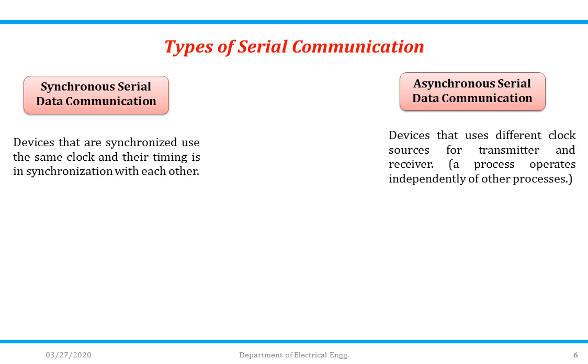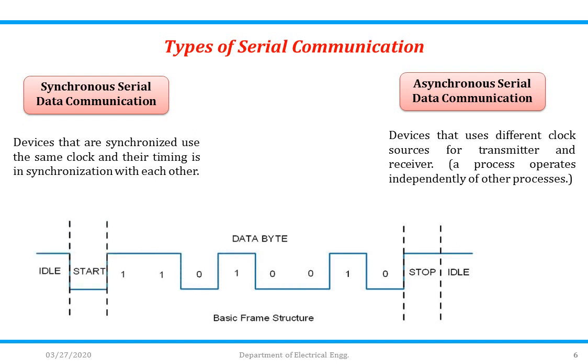Now in this mode, data is transmitted with start and a stop bit. So therefore here the data transmission, here I have written a start bit, this is your stop bit. Asynchronous communication means each character, that is a data byte, is placed in between the start and stop bit. So whatever bits which are present in between start and the stop, basically it is nothing but a data. Now there are 1, 2, 3, 4, 5, 6, 7, 8 bits. 8 bit is nothing but 1 byte. So therefore asynchronous communication means each character, that is a data byte, is placed in between start and stop bit. The start bit is always 0, so therefore this is what is your 0 magnitude. Stop bit is always high, so that is it is magnitude 1. In asynchronous serial data communication, single byte is transmitted at a time.